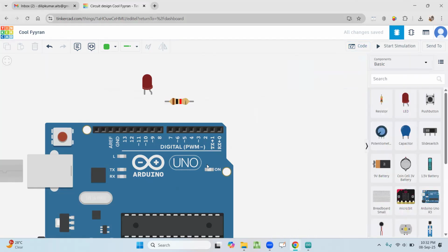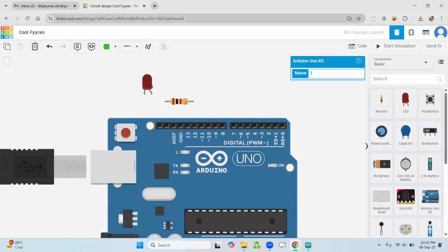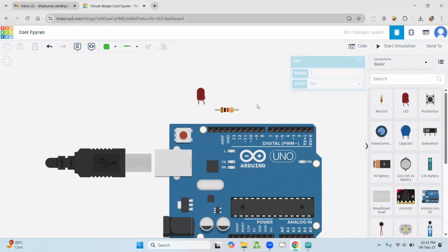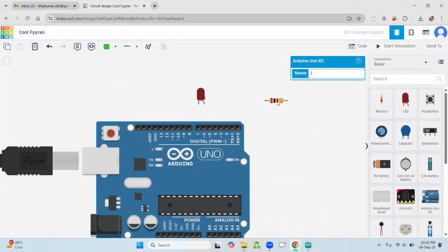Now let us go with the connectivity of the components. In the program, it is shown that number 4 is the connectivity parameter. In order to protect your LED from the major current coming out of the controller, a resistor is used. There is no other reason for adding the resistance for this blinking activity; it is only in order to protect the LED from high current flow.